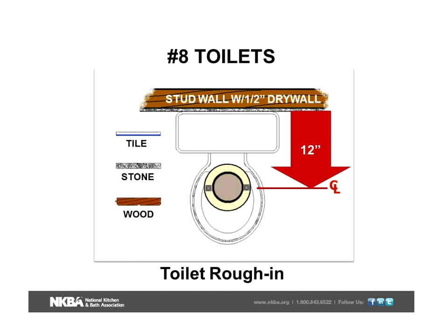Now, here's what happens. Here's our stud wall. Here's our drywall. Unless you tell the plumber otherwise, that will be at 12 inches for that toilet. But you failed to tell the plumber you're putting ceramic tile in on top of whatever the wall material is that the plumber's factored in.